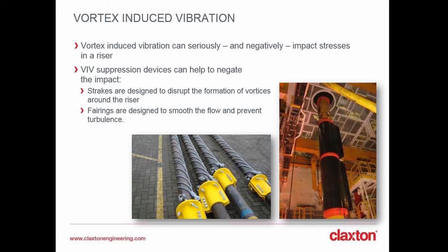And just in summary, when the VIV presents as cross flow, that's when it's the worst potential problem, because you have potential structural damage as well as fatigue. As I say, it's the worst case scenario. What happens is the vortices break one way first and then the other, and that makes the oscillations increase.